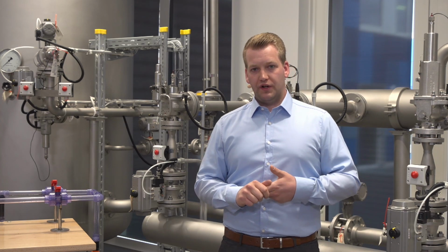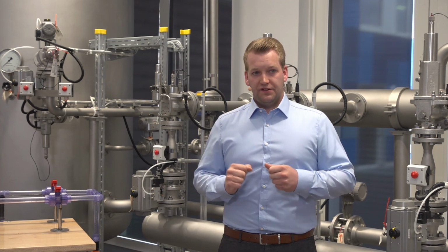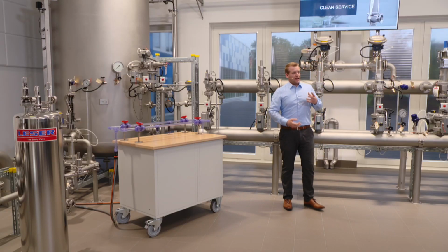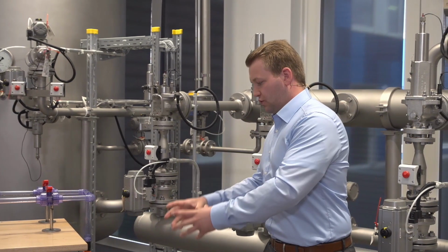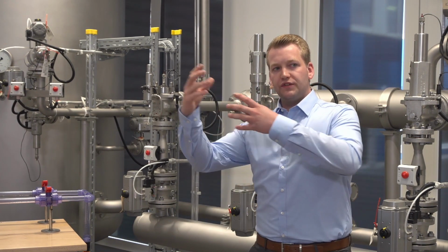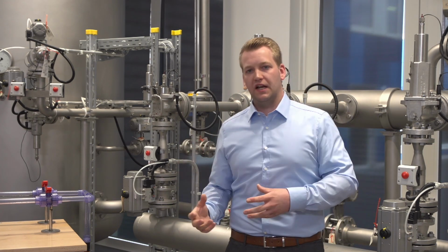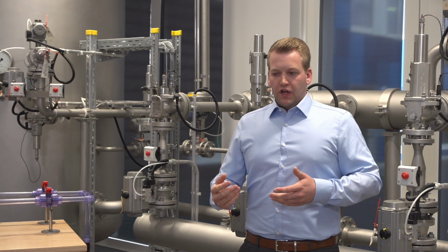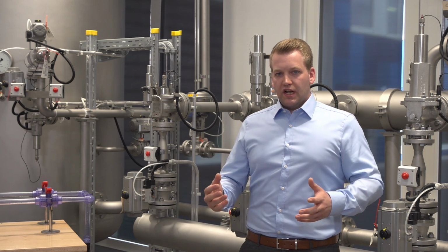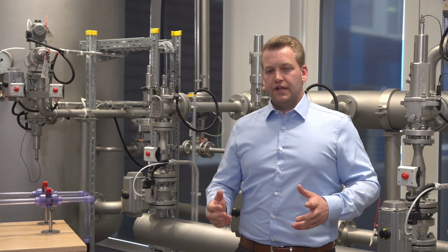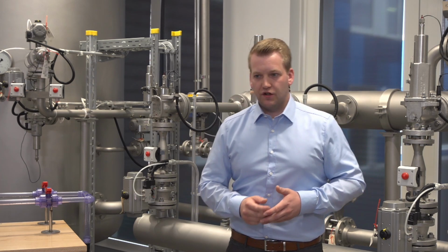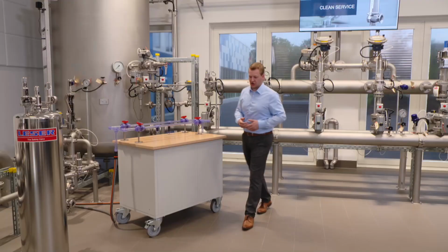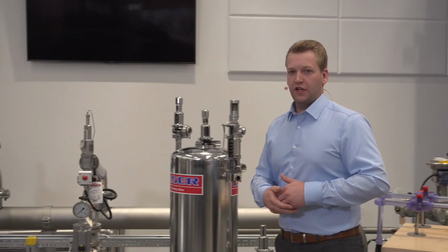Then the third one is cleaning out of place. This means we remove the safety valve because there are spaces that are hard to clean. Then we must remove the safety valve and then we can clean it. So this is cleaning out of place. If we want to have efficient cleaning, there is a term called dead space ratio. What dead space ratio means, I will show you now in a 3D animation, live here in the LESER Chatroom.